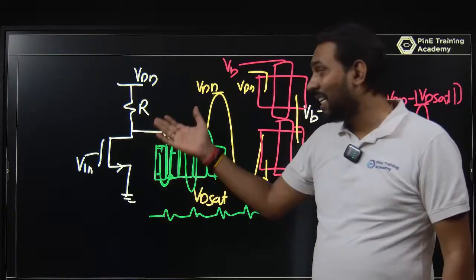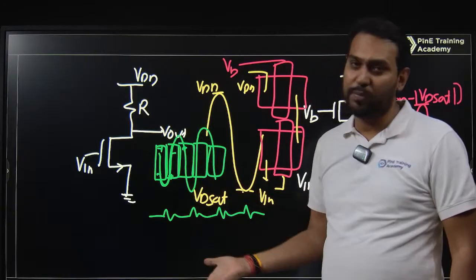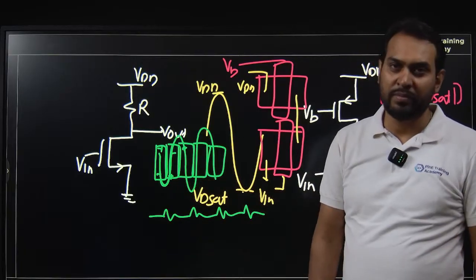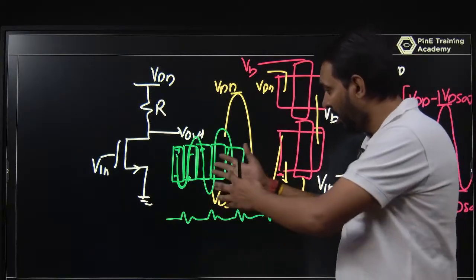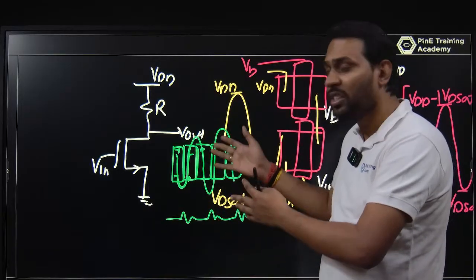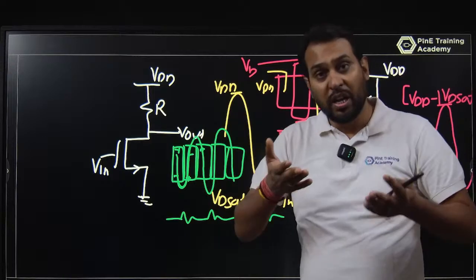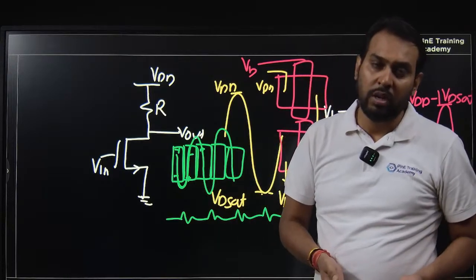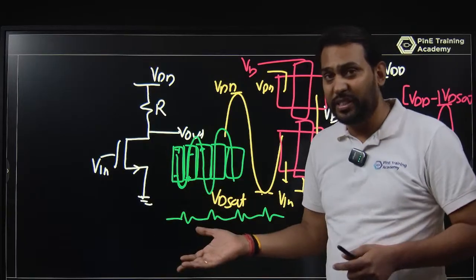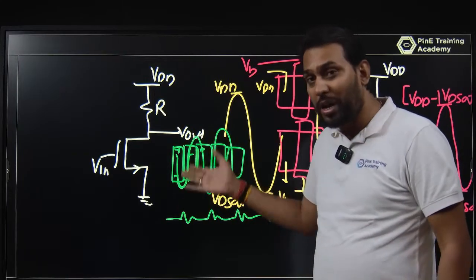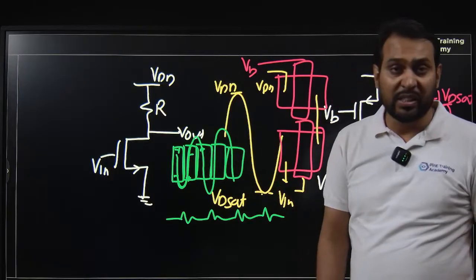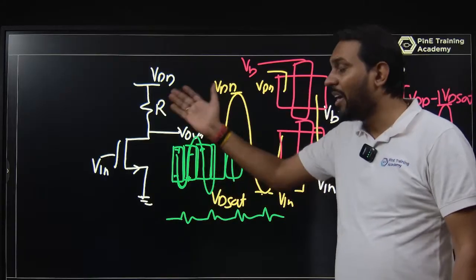Okay, because the resistance will be high, it will take too much space in analog layout design, and it will increase the complexity. So you are increasing to 10 poly. Let's say poly resistance, if I am not using metal resistance. Metal resistance is in terms of 1 ohm. It is very small, less than that, this is 10 milliohm. So poly will provide a higher resistance. So you are using poly resistance and arranging it in such a way that it becomes a series, and it becomes 10 kilo ohm.